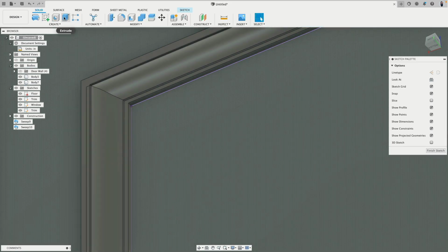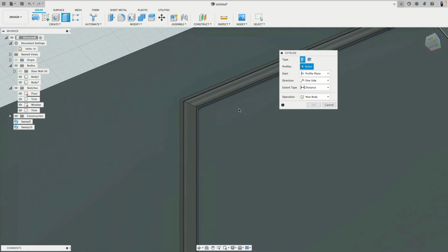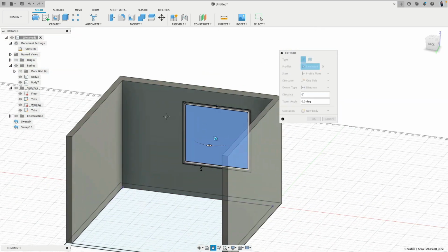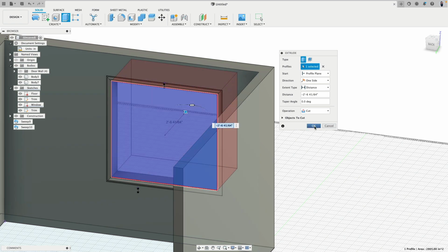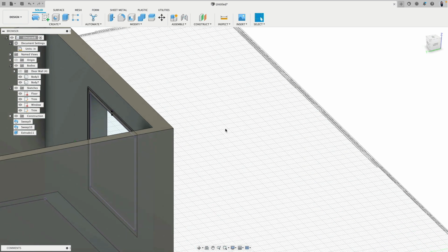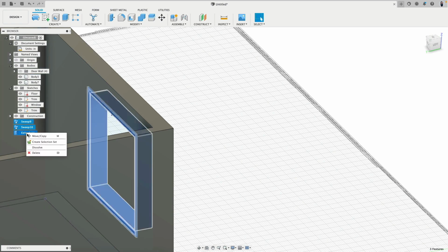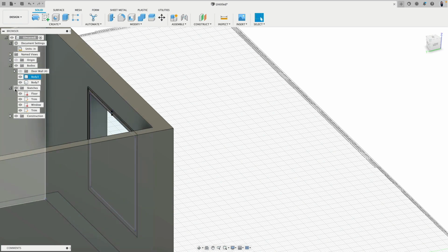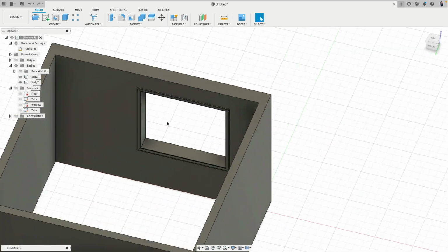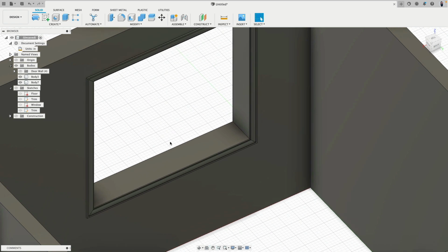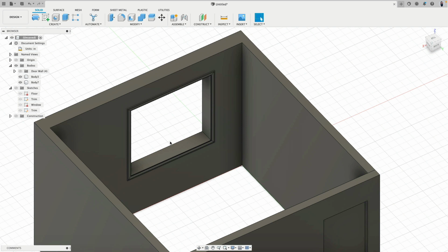And then when I go solid and extrude, I should then be able to, in top view, select this and extrude this and cut through. Boom, there. Right click, dissolve these things. I can turn all this off. Yeah, there you see? Step by step, we're blocking all the stuff out. Pretty easy. Cool. Okay. Now let's do a speed modeling actually for the window.